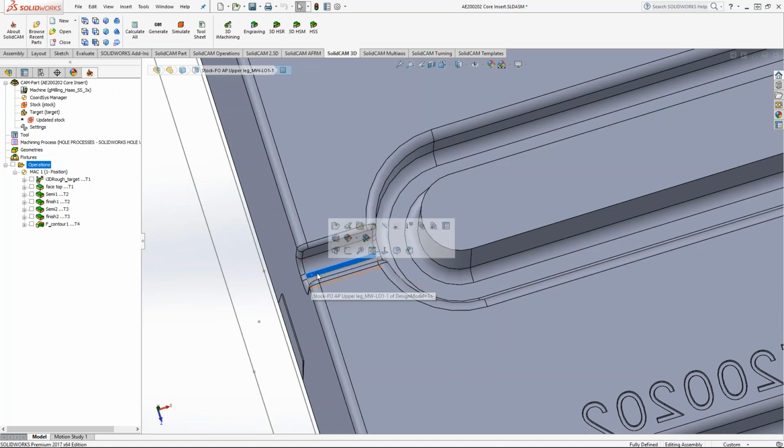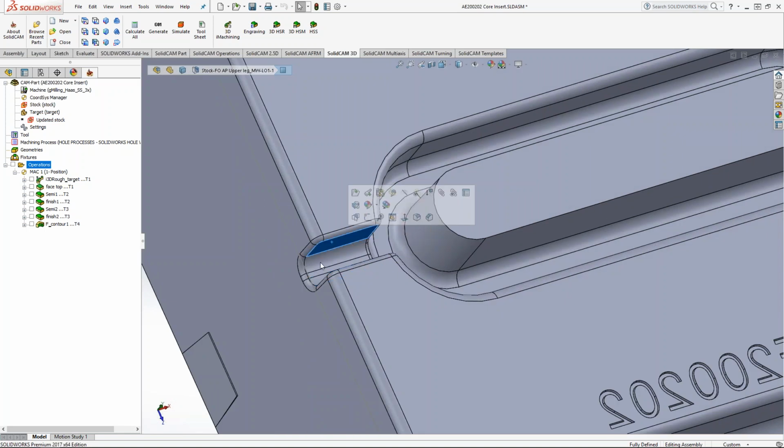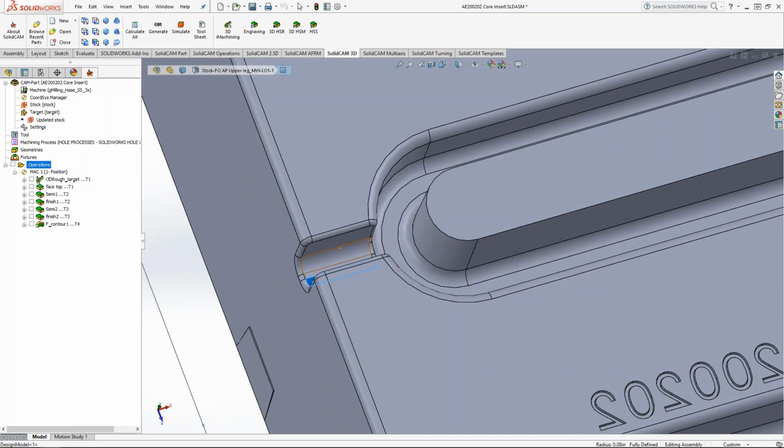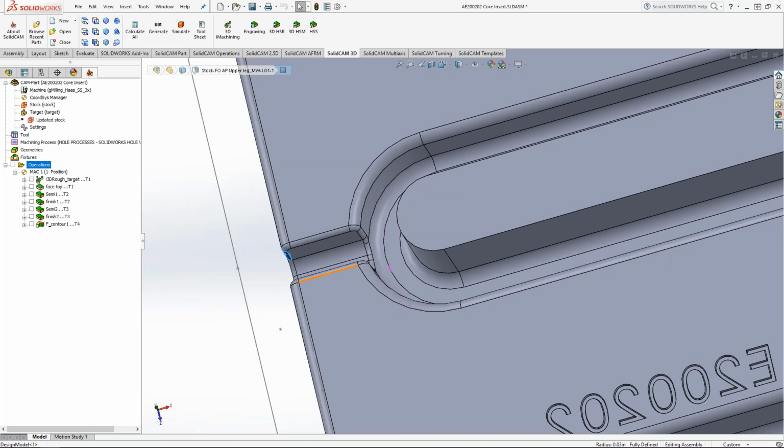Two different tool paths: one constant Z for this one and a linear for this one. And then on these fillets, I may come in with a morph between 2 boundary curves, because that would give me a pretty consistent tool path and a nice finish on that fillet around that transition.